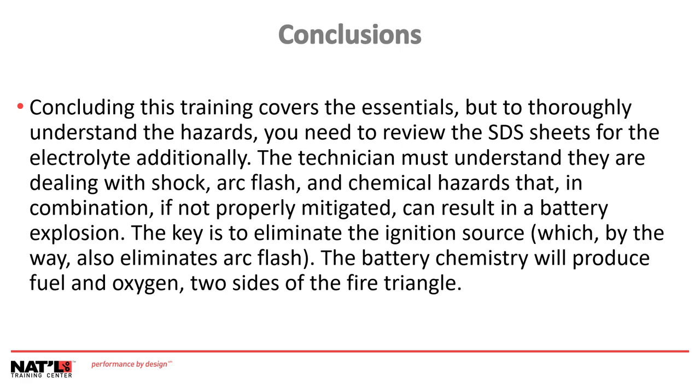In conclusion, this training covers the essentials, but to thoroughly understand the hazards, you need to review the SDS, or safety data sheets, for the electrolyte additionally. The technician must understand they are dealing with shock, arc flash, and chemical hazards that, in combination, if not properly mitigated, can result in battery explosions and fires.